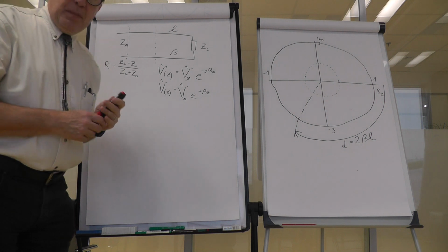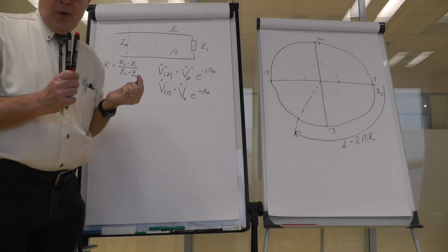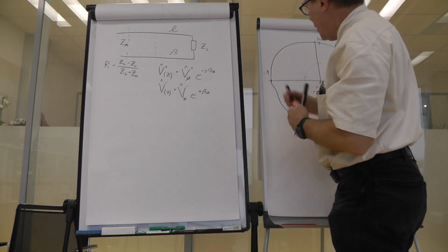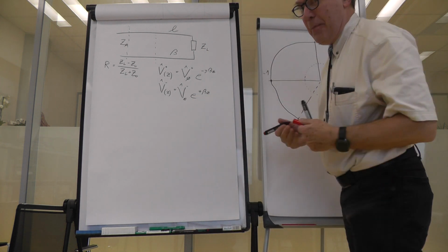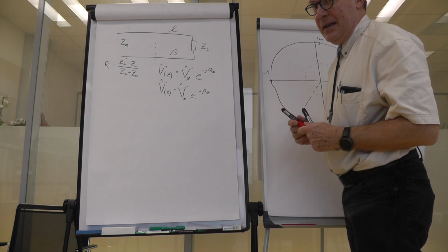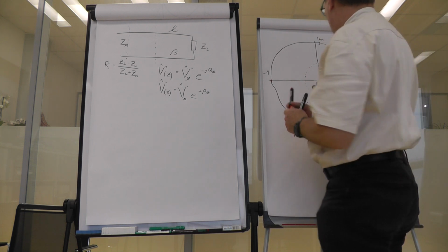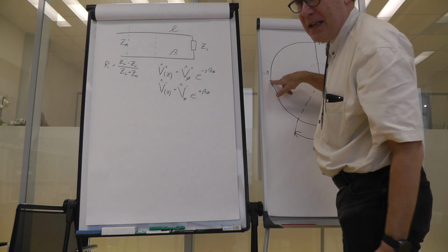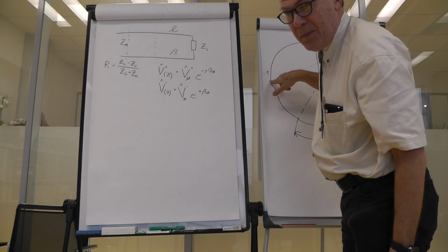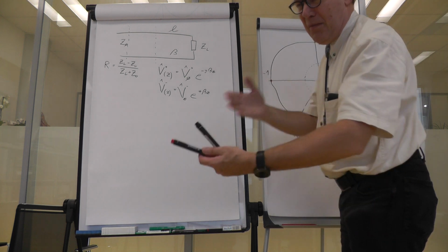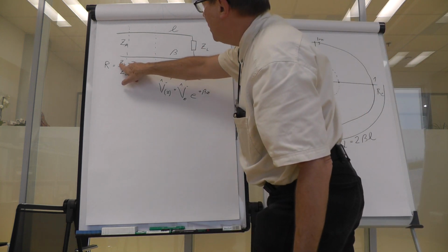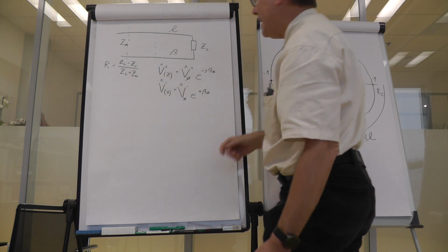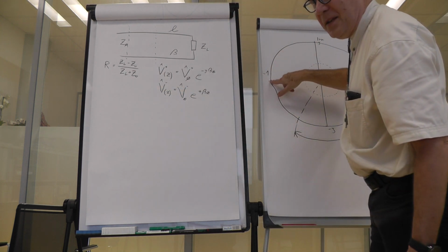There are several special cases I would like to show you. For example, we have a reflection coefficient of -1 over here, and this is something which is a pure short. Remember, if Z load is 0, then we would have the coefficient of -1, so this is a pure short.